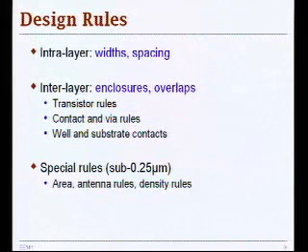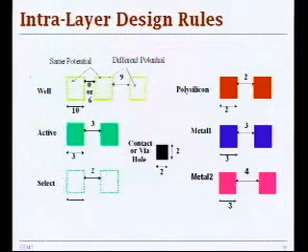And if you don't have enough density, today's processes normally have automatic filler insertion, that you have basically a dummy fill that's mostly done by inserting decoupling capacitors for supply lines, but also you can add other dummy structures for other metal layers from metal 1 all the way up to the highest layer you use.